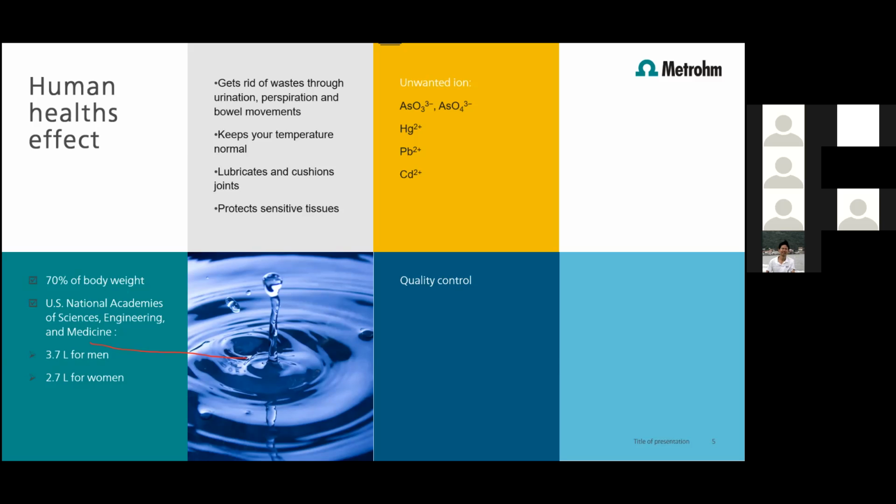Mm-hmm. But major products provide equipment that can test both of them. First, we can test arsenic 5, and we can test the total arsenic, and we subtract arsenic 5 from the total arsenic to get the remaining arsenic 3. Okay. Thank you.